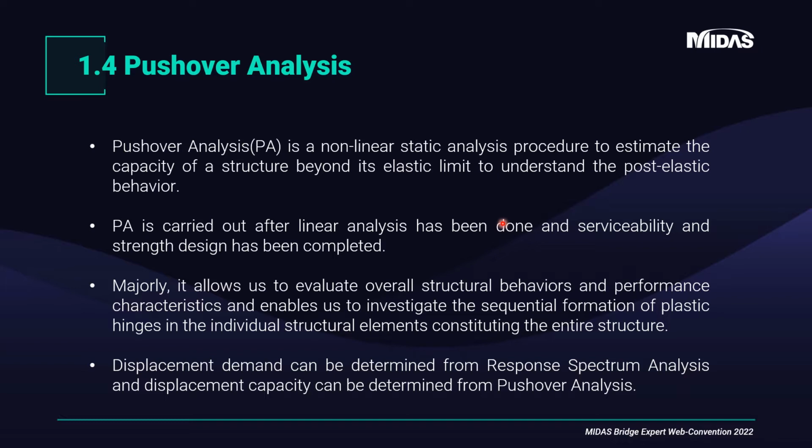This is generally carried out after the linear analysis, where we freeze the sections and reinforcements, and we complete the serviceability and the strength design. It majorly allows us to evaluate the overall structural behavior, the performance characteristics, and the sequential formation of the plastic hinges in the individual structural elements. So all this can be evaluated. Finally, when we arrive at the displacement capacity by pushover analysis, we can compare it with the displacement demand that is determined from the response spectrum analysis.